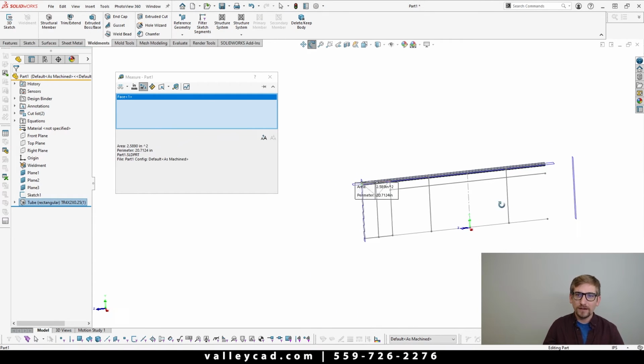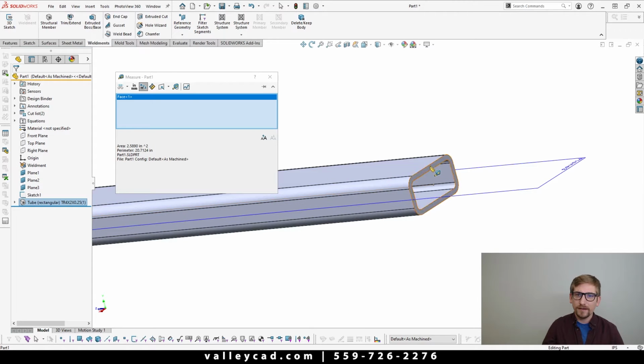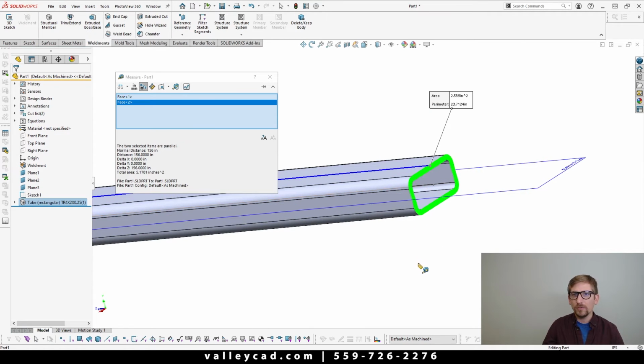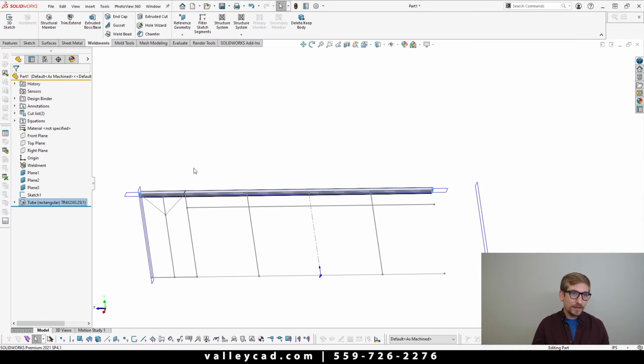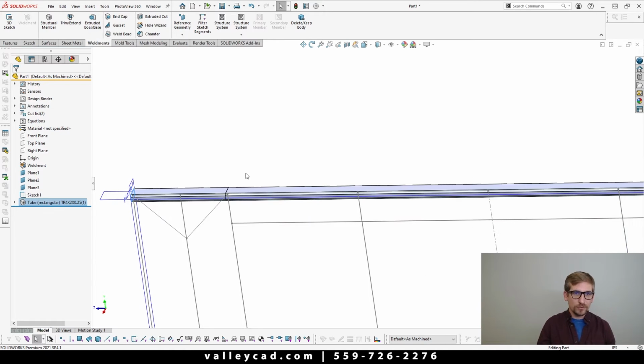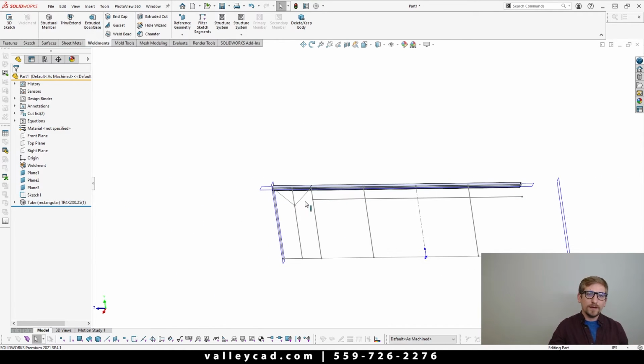Because if I click from here and I come over onto this side, we're dealing with 156 inches. Okay, so standard lengths they could get in tubing is 240 inches, right? So technically I could actually make this all as one unit, not separate two, but for the sake of needing to mirror this over to the other side, I am gonna make it as a separate unit.